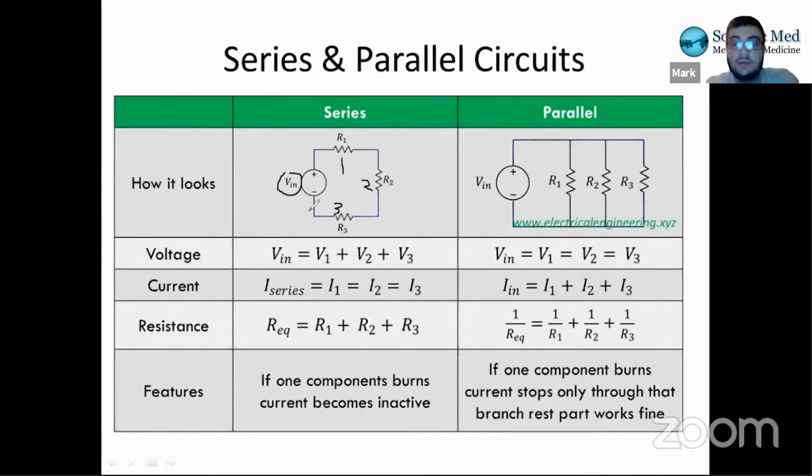And this is, again, if you want to think of it in a Kirchhoff's Law sense, if this is a node, this is node 1, there's one line going in and there's one line going out. If there's one line going in and one line going out, that means both the line going in and the line going out must have the same current, right? The current hasn't changed because there's only one going in and one going out. Okay. And the resistances are very simple. You just add them together.